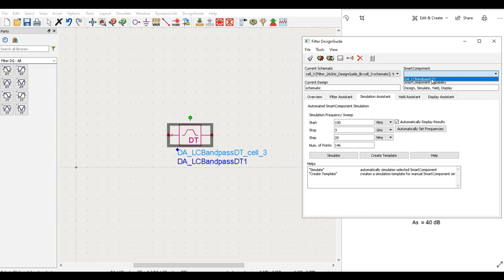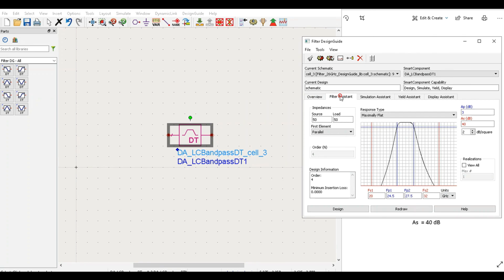We select here the bandpass component. This is very big here, because then we'll go back again to our filter design. You can see that it's already giving us some design, but for this it's using a maximally flat filter design, but we can use any type of filter design like I explained before. We have the Bessel, Thompson, the Gaussian, different types. I only like using Chebyshev. So if we put this now, I will click on design.